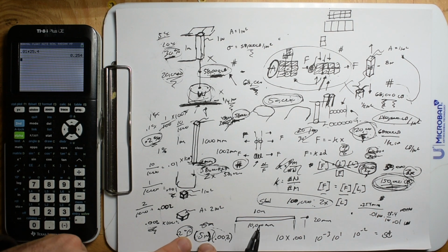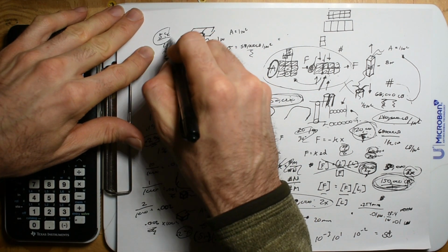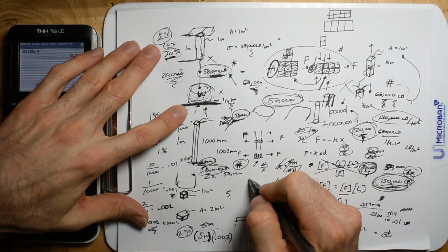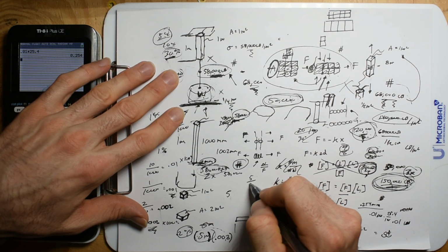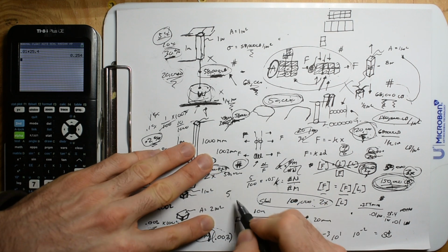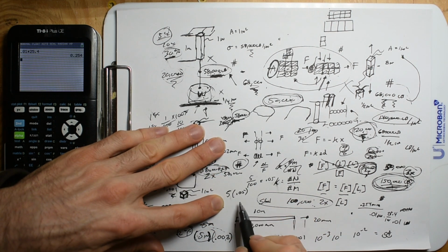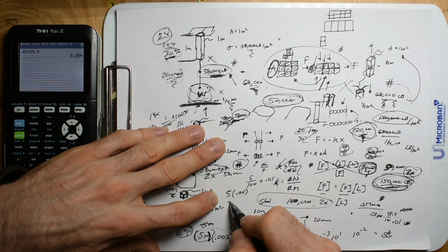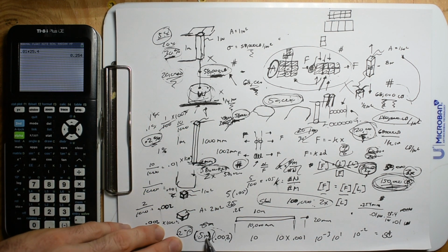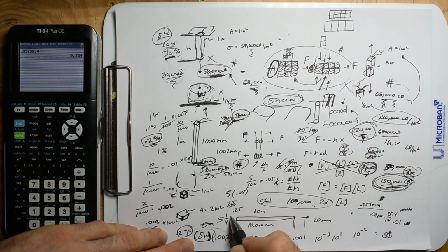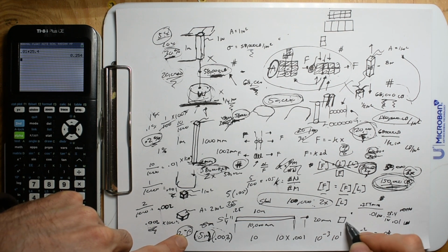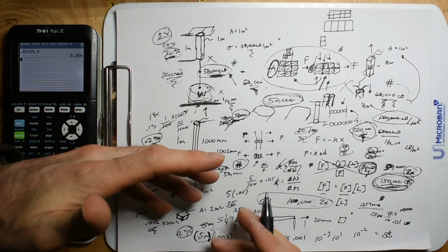What's the most I can stretch this bolt if I keep within this 5%? So I'm going to go 5, and then 5% is, take 5 and divide it by 100. That's going to be 0.05. So take 5 times 0.05, and I got 25, and then move the decimal, 0.25. So I can move this bolt a quarter inch. So I could stretch this bolt to 5 1/4 easily. That's why I want to do this, because obviously I could read that with my calipers.